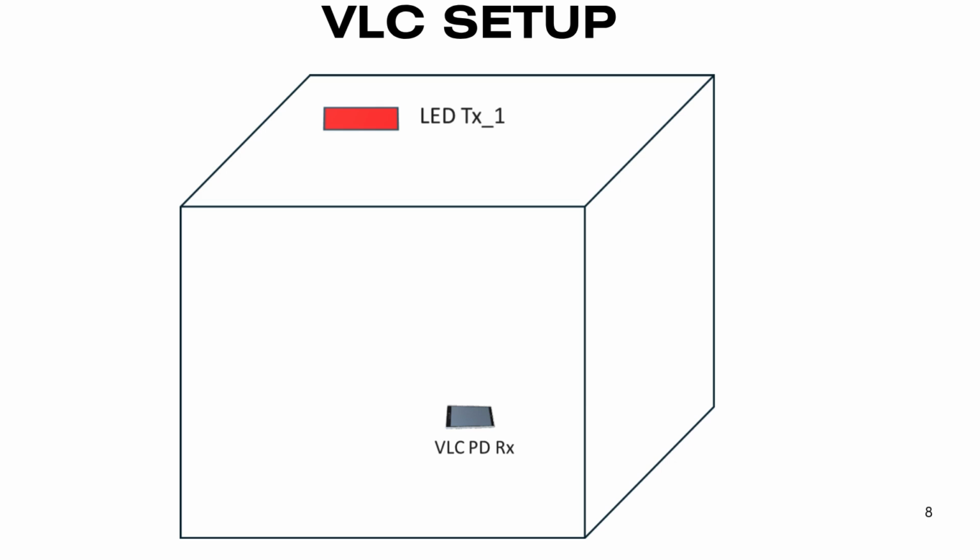Actually, the area of a photodiode which can comfortably convert the optical light energy into electrical current is in centimeters, so we can pop it into any handheld smart device without extensively modifying the internal or external design of the device. Also, photodiodes are sensitive to light and provide reliable performance in noisy environments, therefore suitable in different applications and use cases. But the best of all is the optical to electrical conversion ratio, which we technically refer to as responsivity.